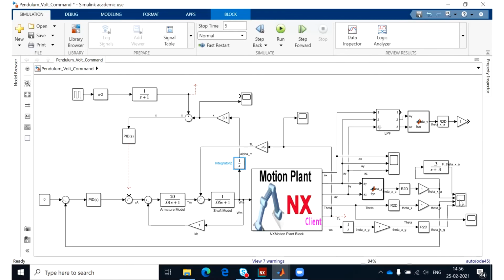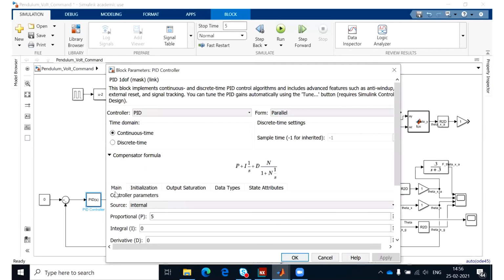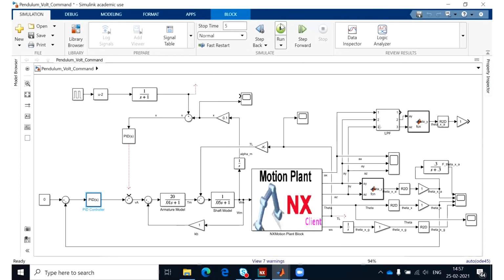I can also show you what we have here in the scope. Let's change back the parameters of the controller to the case that it doesn't shake too much. I think it was 3 or something, or maybe even less, maybe 1. Also, you could have a D term. It will improve the performance, but for now it's not needed because I wanted to give you the idea. We are not going to design a good controller here. It's just about the idea.